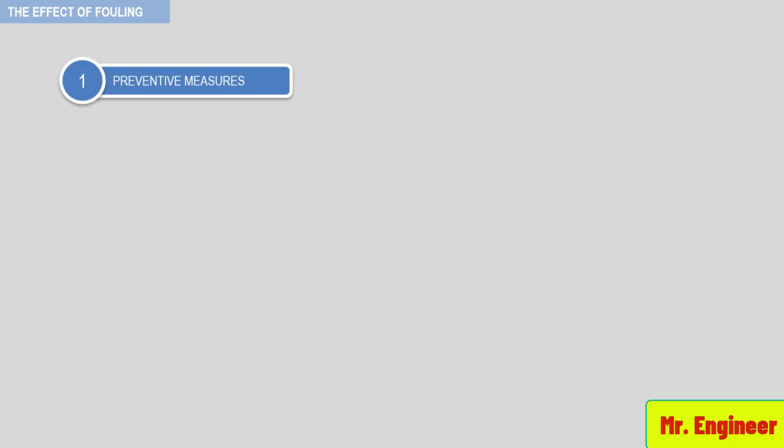What I will describe for you now are proven methods for preventing fouling, so this part of the video may be very useful for you. First thing to remember and keep in mind is that accurate control of process conditions can prevent fouling in applications where polymers can be formed. Control of temperature is usually the most important.